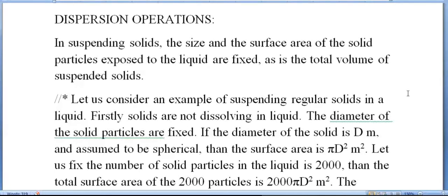As these bubbles are rising, upward currents are created, and once your system is established and has come to a steady state, you add the fine powders of the catalyst to the reactor slowly, so that the upward currents will prevent the settling of solids. We don't want solids to go to the bottom of the container because it is a catalyst. So it should be dispersed. It should be present at all corners in equal concentrations in the bulk of the liquid. Then you can pump the gas, and the reaction takes place.